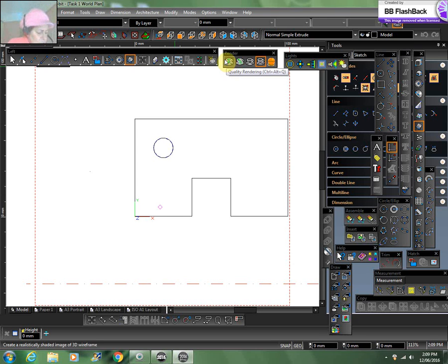This extrusion tool sweeps a 2D profile in a plane perpendicular to the work plane. To create a 3D object, select the simple extrude tool and select a profile. Then you click on the profile. Use the keyboard to access the height. Here it says height. You type 20. So the height will be 20, and then you click this lock to turn it blue from yellow.